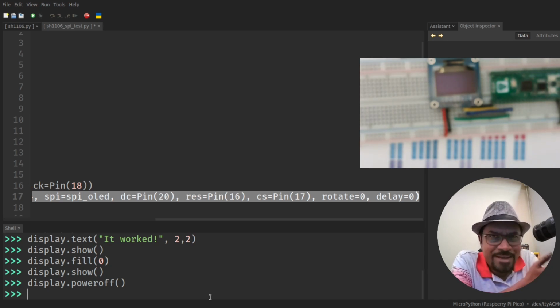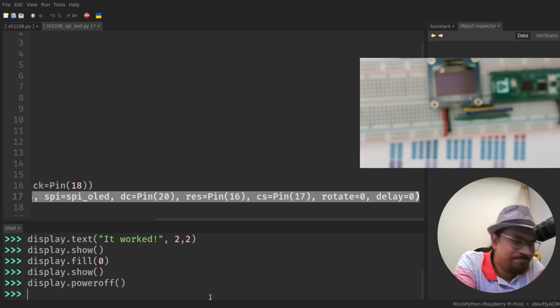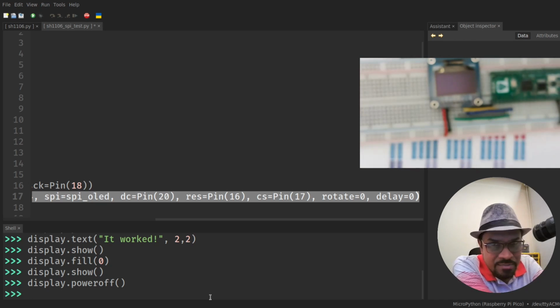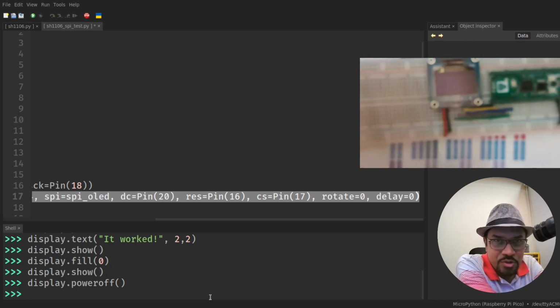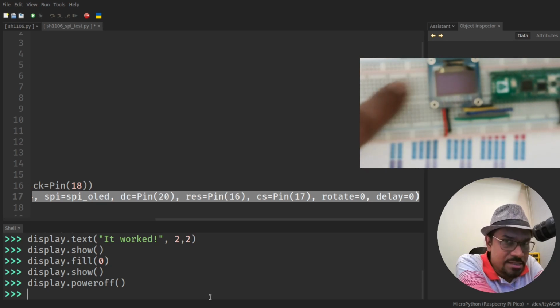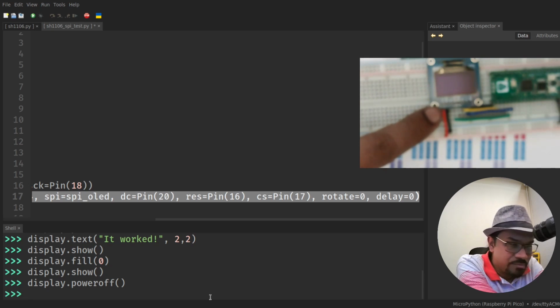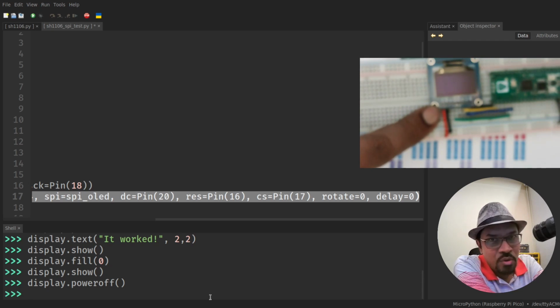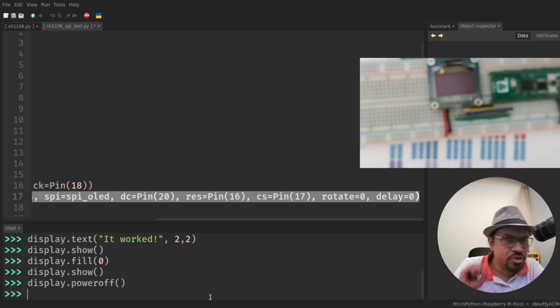You can now connect sensors. The basic thing you can do is connect a DHT22 or DHT11 sensor and read the temperature, humidity, and you can display that on the screen. So you can use any GP pins to which you can connect them, and you can display it. So you know how to display something using the SPI interface using SH1106, which is based on an 8-pin OLED display. The next I want to show you is the one with I2C, right?